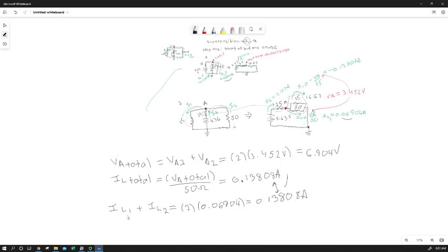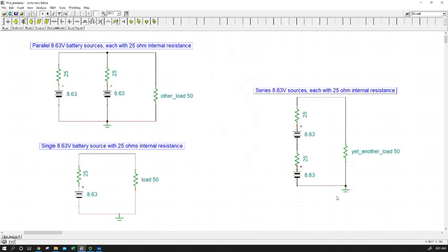A lot of times, the lower the internal resistance, the higher the current capability, the more expensive the source. But as you can see in terms of maybe long-time power dissipation in a lot of these circuits with high internal resistance, especially this one, where we might just keep adding these imperfect sources in series to get our voltage drop over the load, every time we add them, we're adding a series resistance that is comparable to the load if we have a low load resistance circuit. So that can get us into a bit of a no-win loop, because we end up dissipating more energy over the internal resistance of our sources than we do, or a comparable amount to what we use in our circuit, and that is very, very wasteful of energy.